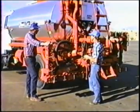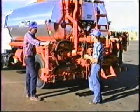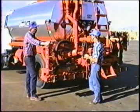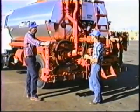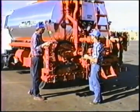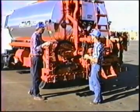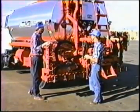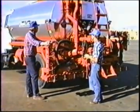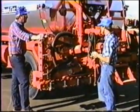You need to understand what's going on back here so that if the computer quits, you can regulate it manually, or you can determine what the problem is with the computer. You can see that for the computer to know how to make its adjustments, it has to have information. It has to have gallon per minute information, travel speed information, and bar width information. If it has all that information, then it can do what it needs to do if everything mechanically is functioning. Any more questions about spread rate or spread rate regulation?